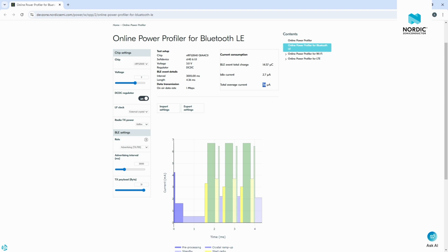Optimizing the scenario where the device is in advertising role, which is going to be a lot of its life cycle, is actually in the advertising role. So we need to really fix this and change it from 141 to 7.6. Sorry, this was 100. So you can see 141 to 7.6. That's about a 20x factor of reduction. So again, that will be one trick we will do in the application to optimize for low power.